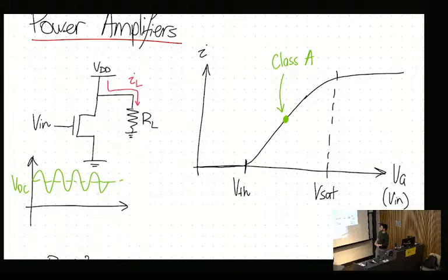Yes. So with the tap analogy, I've effectively just left the water running, and the water is always running. I'm just going from slightly more to slightly less, but current is always flowing. This FET is always on. So it's very inefficient. But what's a good property of class A amplifiers? What does it have going for it? Yep. Yes, linearity. It's very, very linear because you can see that the amplifier is always in an on state.